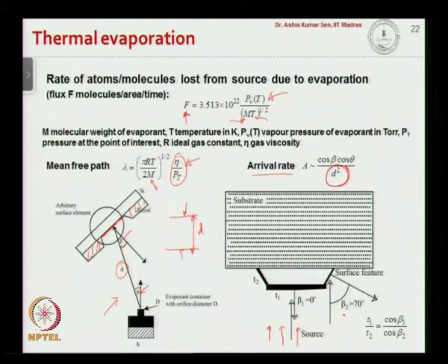Let us say beta 2 is the angle of those two inclined surfaces, and for this surface beta 1 is 0. So the thickness of the evaporated metal layer that we end up with, T1 over T2, will be cos beta 1 over cos beta 2. So the thickness would depend on the orientation of the substrate with respect to the metal source. With that let us stop here.